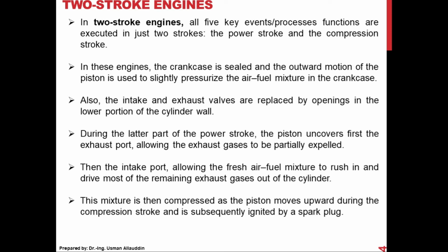In four-stroke engines, all these five processes are completed in four strokes and 2 revolutions of the crankshaft, because I told you that for one stroke the shaft rotates 180 degrees, and for two strokes the shaft rotates 360 degrees. This completes one revolution. In the second revolution the exhaust and intake take place. During exhaust and intake, the exhaust and intake valves are open, so there will be no pressure buildup and no power output in the second revolution. So you get power on every second revolution of the crankshaft rotation.